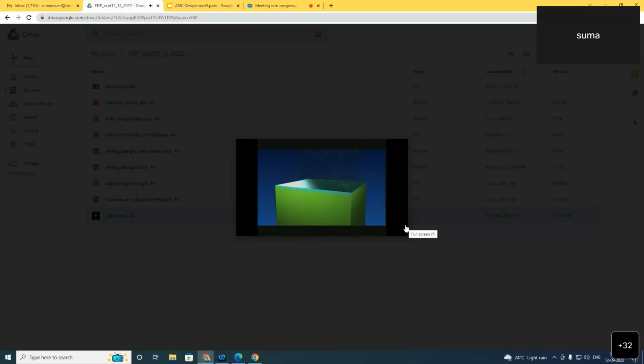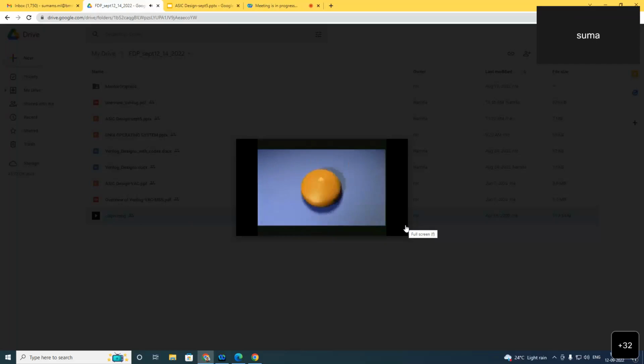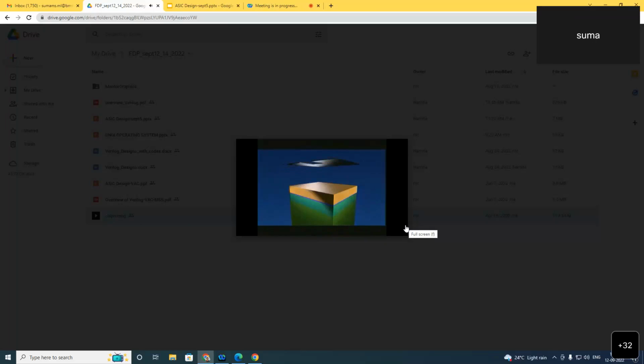First of all, we create a layer of silicon on the slice, 1/100th of a millimeter thick. We then oxidize this silicon layer in an oven, so that an even thinner insulating layer is created on top of it. We then apply a coat of light-sensitive lacquer. We expose the lacquer through a kind of photographic negative, so that the lacquer dissolves in certain places.